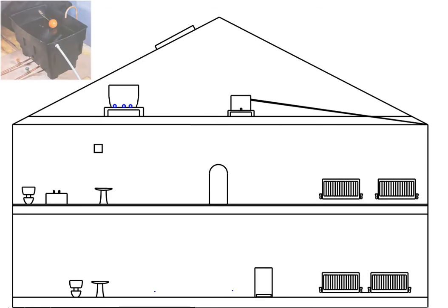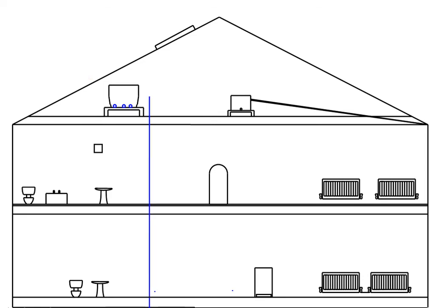To start there, we bring in our rising mains. That goes up there into our water tank in our attic. The rising mains is 15mm in diameter. Then we have our drain off valve, which is here, and we also have a valve over here that shuts off the water going to our sink if we need to change the appliance here or fix the tap or whatever we need to do. That's the way it's shown.